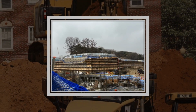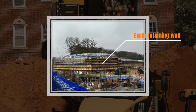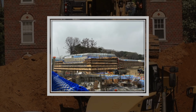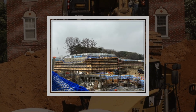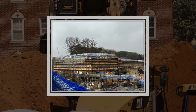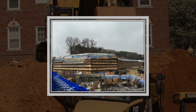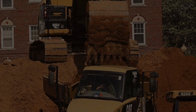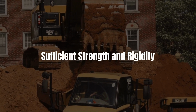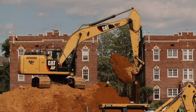The answer is the earth retaining wall. Earth retaining refers to walls that support earth pressure and water pressure, which are made for the purpose of preventing settlement or collapse of the surrounding ground when excavating the ground. The earth retaining wall must have a structure that is safe against the lateral pressure acting during construction and needs to have sufficient strength and rigidity to prevent collapse or excessive deformation of the site of the ground digging.